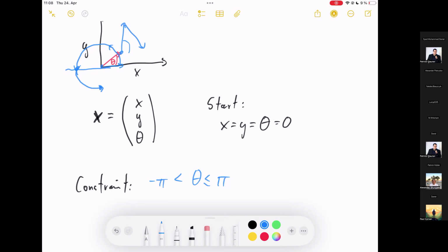So this is an important convention that we are using, and something you need to pay attention to when you start implementing this code and you start rotating the robot. Make always sure that you have valid angles, because if you rotate your robot, I don't know, three times 360 degrees, you still always want to have an angle that is in this interval and not like plus 5 pi or something like this. So always make sure you keep valid angles when you rotate the robot.